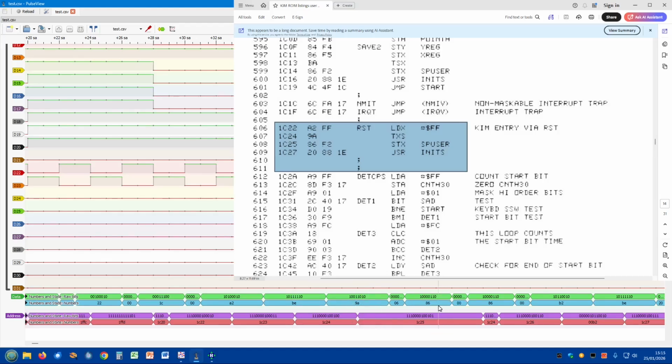Next instruction, which comes from 1C25, is 86. And 86 is store X. Let's look that one up here. The description 8. We're looking at 8. 6 is store X in the 0 page. So store the X register.